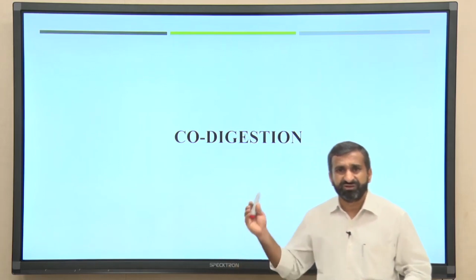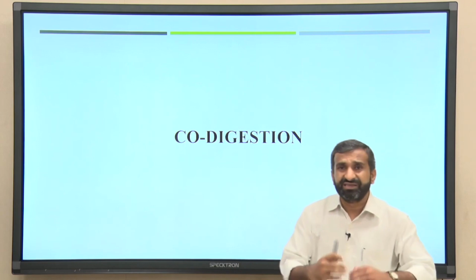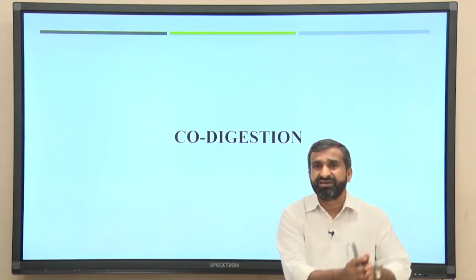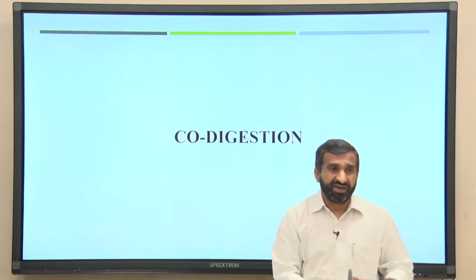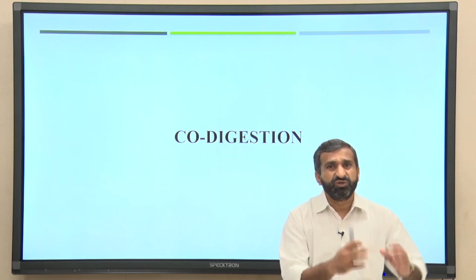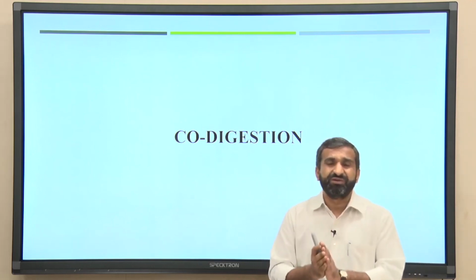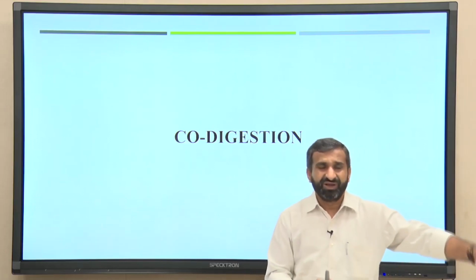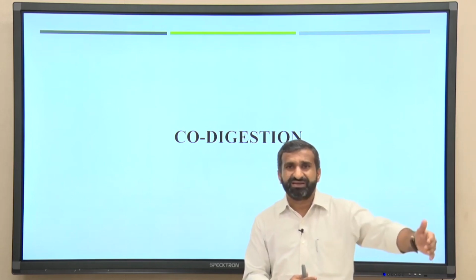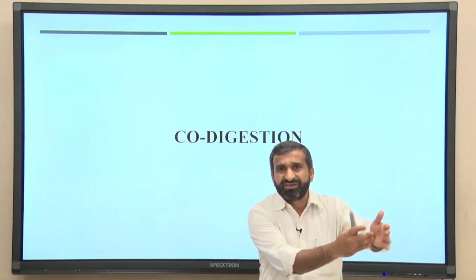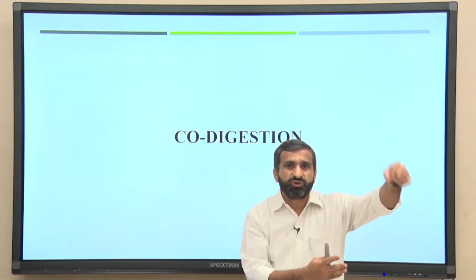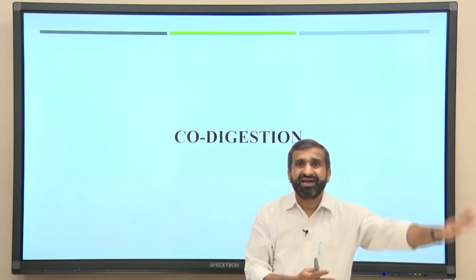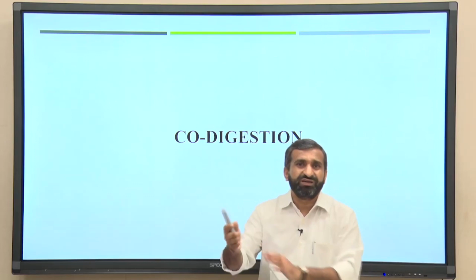Many countries are utilizing such techniques, but in India or developing countries, I believe that physical pretreatment, under which mechanical pretreatment, is more beneficial, and there also shredding or grinding by itself is highly beneficial for the anaerobic digestion process. So, I believe that whenever you install any reactor, you should have a grinder or shredding process. What should be the target of this grinding process? The target is to convert the entire material to a size of 2 mm or less, or 4 mm or less. That should be the target, so that the material size is lowered and it can easily go into the anaerobic digestion process.